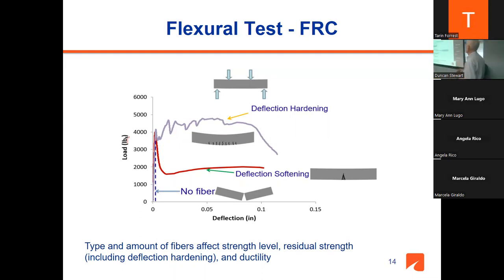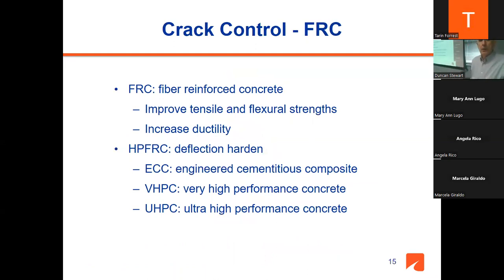So please try to remember this. Based on the fiber, you get some residual strength. After the crack, you still have some carrying capacity, but the level of the carrying capacity depends on what type of fiber and how much we use. So we say that to control cracks, we can use fiber reinforced concrete.